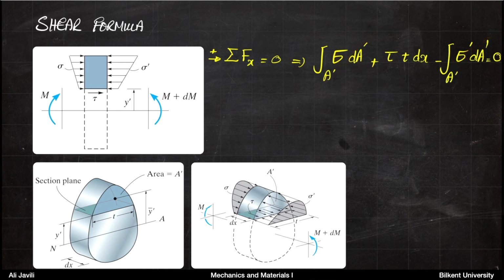And then the effective force you get at the bottom would be this shear stress times the area of that section. Now, the area of that section would be the thickness T times dx, the width, or that incremental width that we chose.